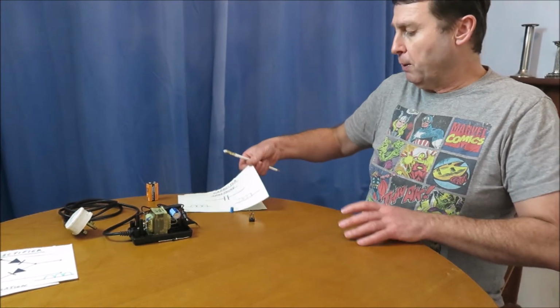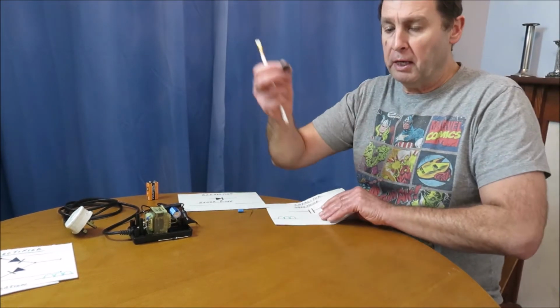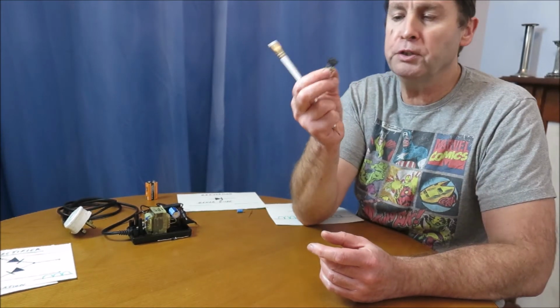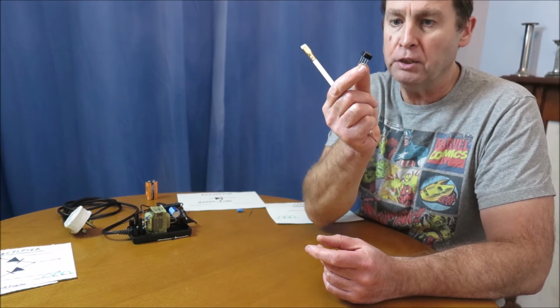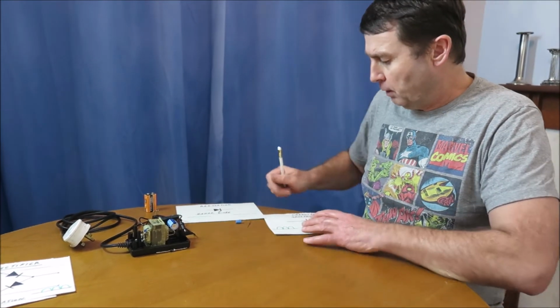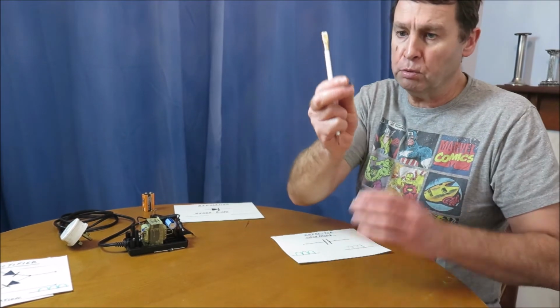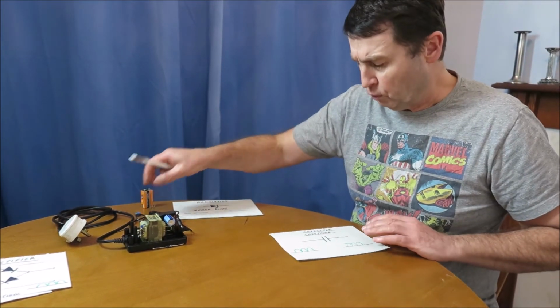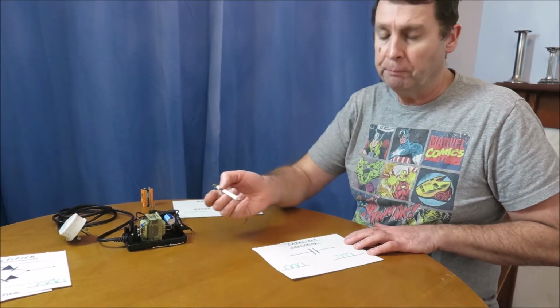Next, we put a capacitor in. Oh, what I forgot to mention, if you didn't want to use 4 diodes for a full wave bridge, you can actually buy a bridge package and that contains the 4 diodes in that package. So, a capacitor, which looks like this. We've seen capacitors in my other videos, and this is one of the uses for them. Now it's a smoothing capacitor.